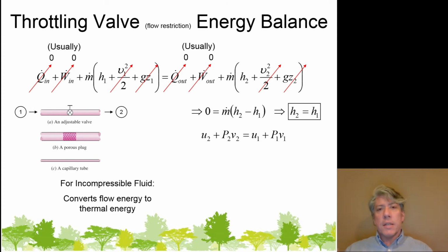Did you know that when you take it to the dynamometer, you put it on it, and you make that car do work turning that drum? Basically, that drum is a hydraulic pump, and the hydraulic pump is just taking in hydraulic fluid, compressing it, and then that fluid just gets dumped across a valve. So basically, the fluid pressure just drops across a valve, a flow restriction, and what happens to the temperature of the fluid is it goes up.